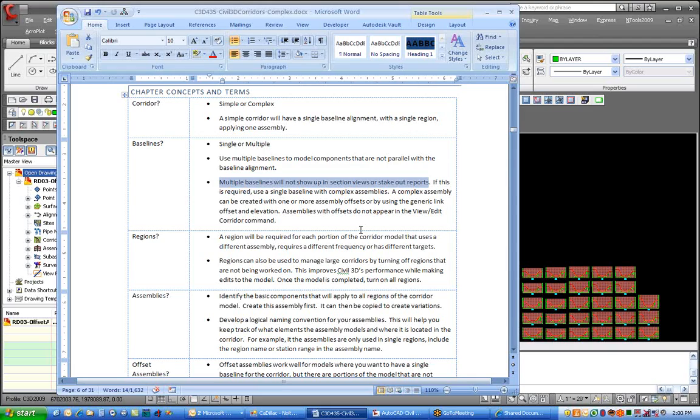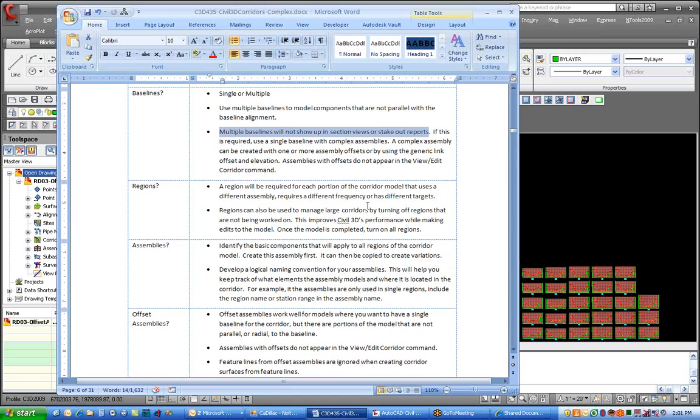What was explained to me is that for 2011, instead of being done as sections, the corridors are going to be extruded as solids, kind of like the pipe routine does. I'll actually extrude it from section to section. Based on that information, you should then be able to draw a line anywhere at any station or any value, and any corridor element that shows up within that, you should be able to sample for a section. Okay, so hopefully that is the case.